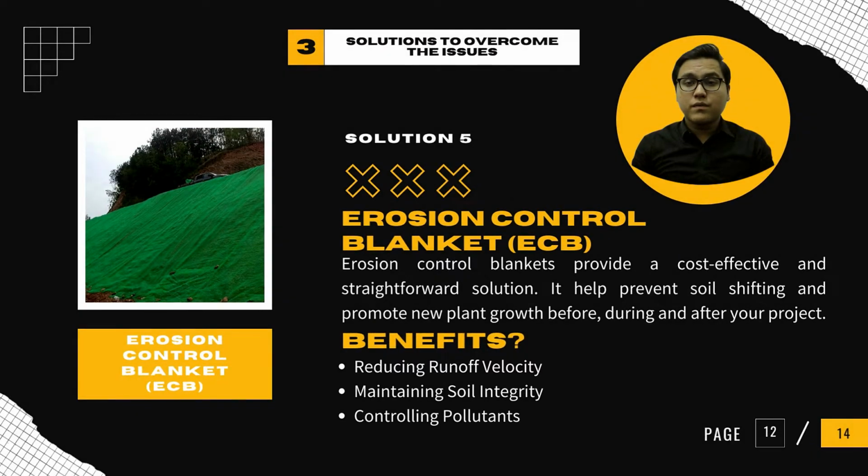Next, as a solution to land pollution, we can use erosion control blankets, also known as ECB. ECB are typically biodegradable open-width blankets that provide temporary cover and support for establishing vegetation on bare soil areas. ECB helps to maintain the soil that is covered and prevent landslides and soil erosion from happening.